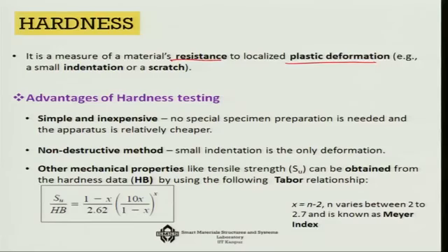Secondly, it is considered to be a non-destructive method, because you are really making a very small indentation without affecting the overall sample. And finally, from the hardness test you will not only get the hardness, but also some important information like the tensile strength. So, this is a very important thing that can be obtained from the hardness data.